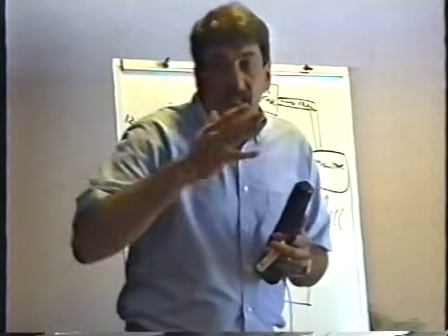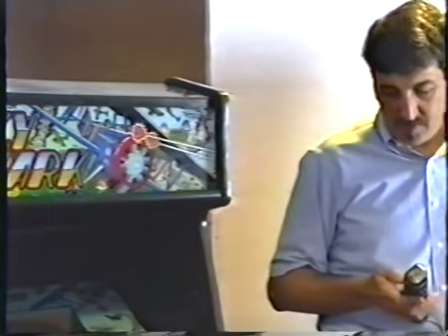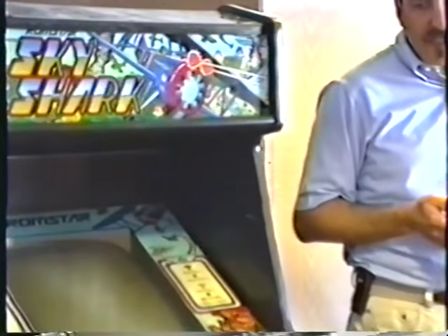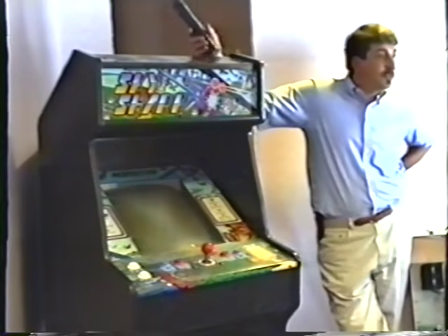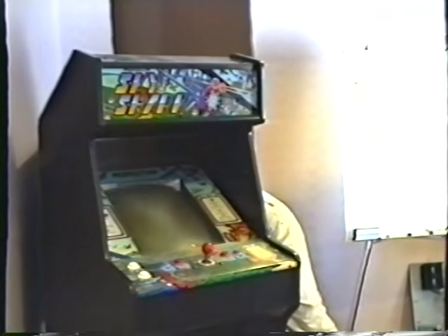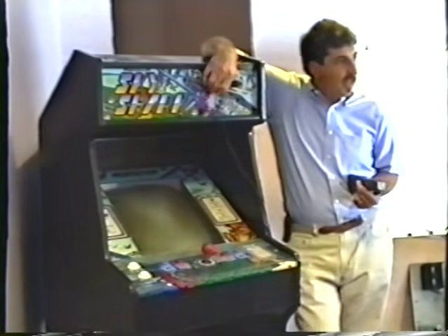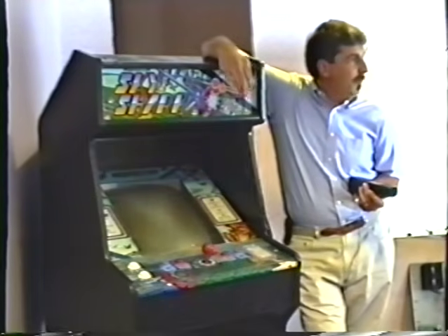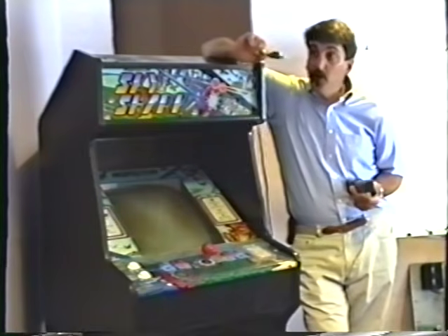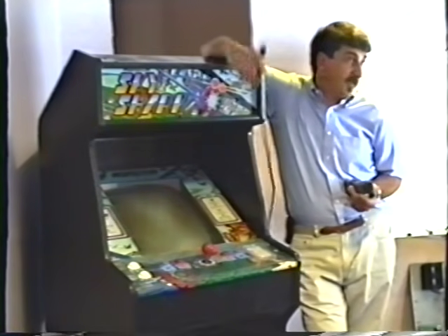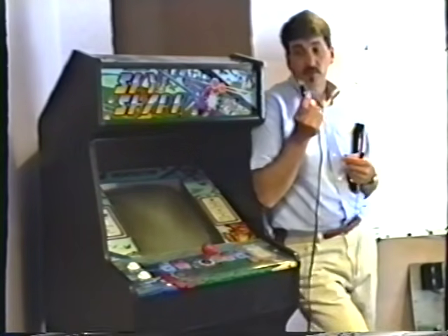Well, let's say you get to the game and you know, here's a typical problem with a game. You plug the game in. In this particular game, it does nothing. In this particular instance, this game does absolutely nothing when I plug it in. When I plug in the main power cord here into the wall, no lights, the marquee light doesn't light up, it doesn't make any game sounds, it's completely dead. The first thing you want to do is to check the power cord. This is obviously pretty simple, and I'm sure that you've had this problem many times. And in this case, this is what's wrong with it.